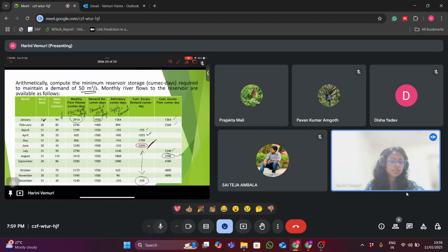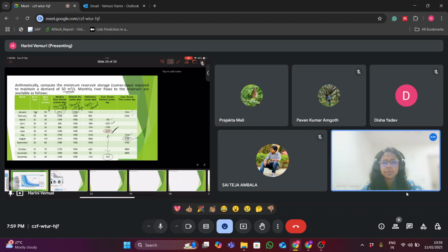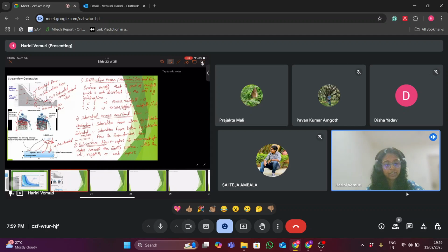Now in this lecture we have talked about stream flow, how the water from precipitation will reach stream flow, and how it varies with time. We have also seen different ways the water will reach the stream flow, like saturation excess overland flow, Hortonian overland flow, subsurface flow, etc. And what are the types of streams? Also, how you measure the stream flow: we can first measure the stages and establish a stage discharge relationship.